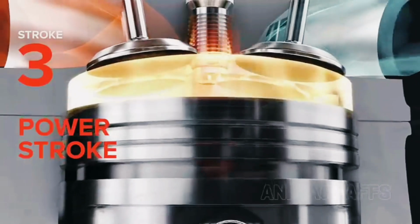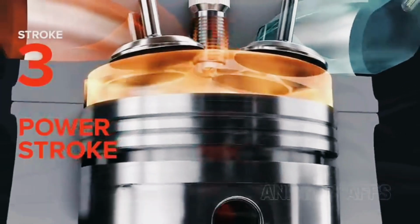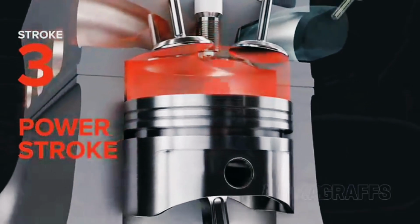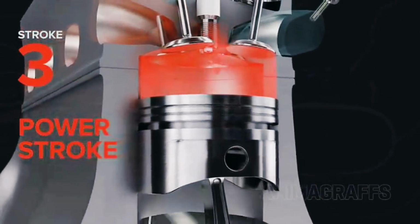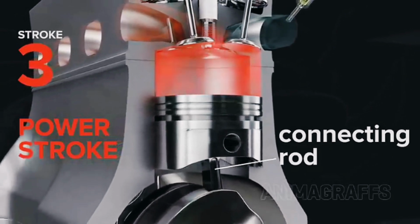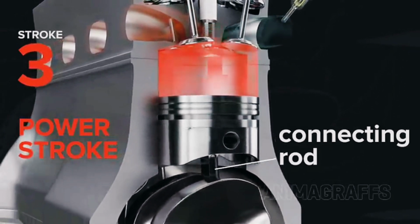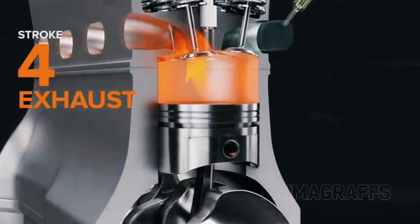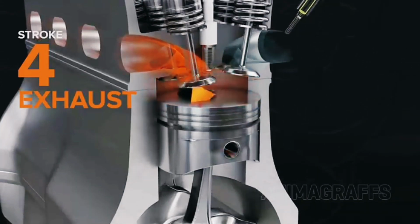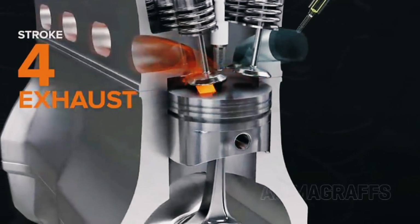Then, the power stroke. An electrical spark ignites the compressed fuel and air mixture, and the resulting combustion forces the piston to the bottom of the cylinder again. The connecting rod transfers this power to the crankshaft. Finally, exhaust. The piston comes back up, pushing the spent mixture out through open exhaust valves and the exhaust port.